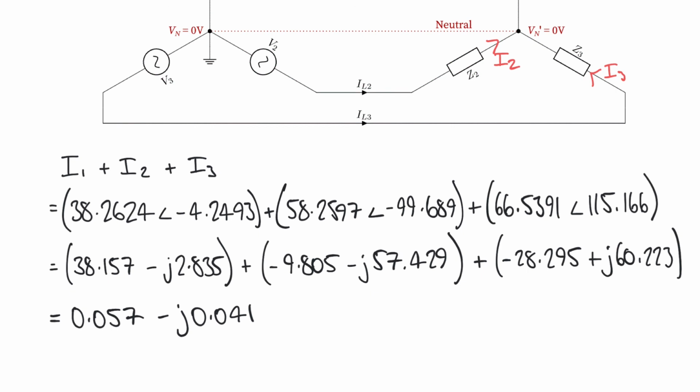The downside is that it introduces rounding errors that compound as we go back and forth between those two forms. But we can hopefully see that we've got something that's near enough approximate to 0, and so this check seems to hold valid, that we're conserving Kirchhoff's current law when we get that result.